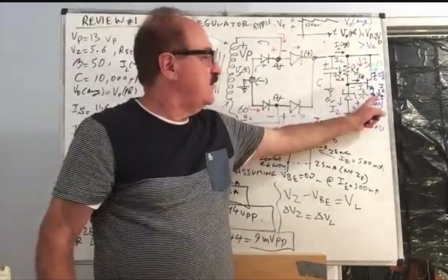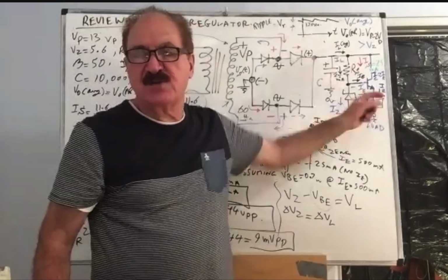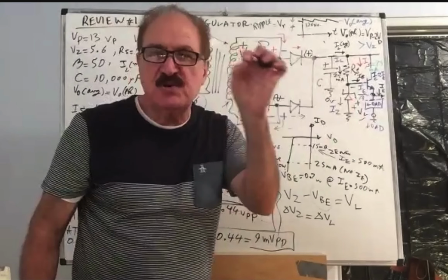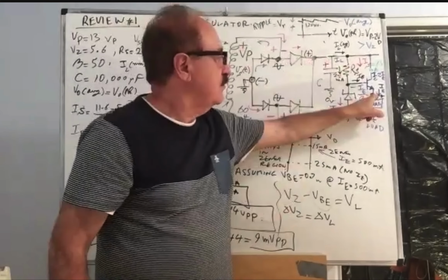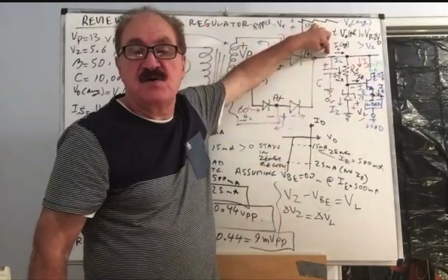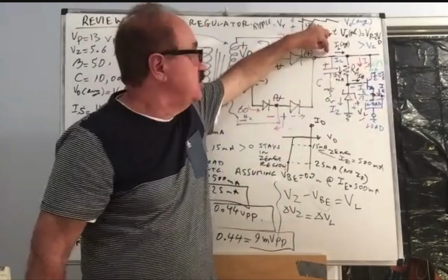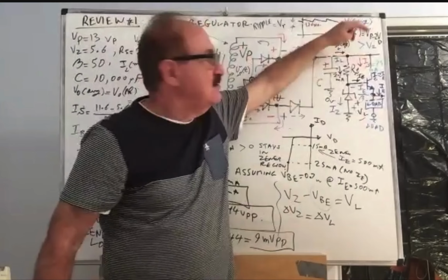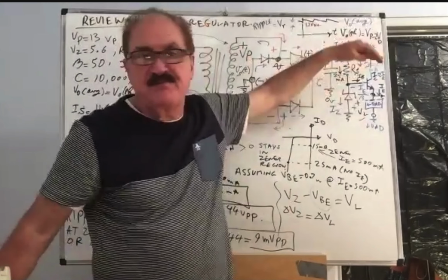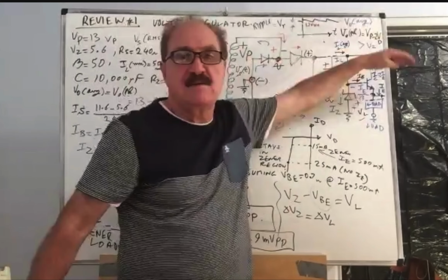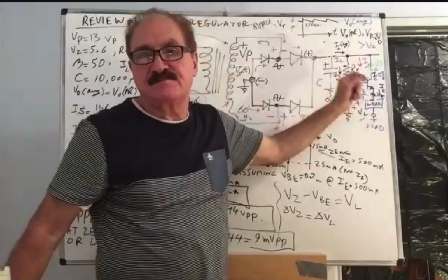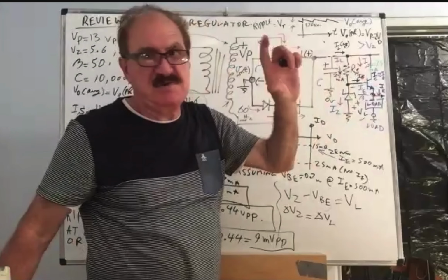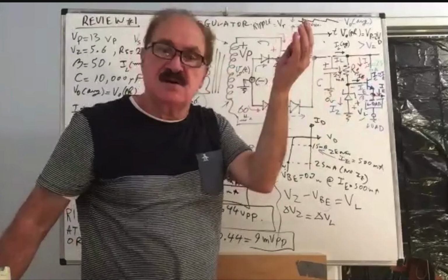Here we are getting a 4.9 volt regulated voltage with only 9 millivolt residue on it. It will not see the 440 millivolt residue, the main ripple at the collector, because the collector has no connection to the emitter. Collector can play, emitter can stay solid. VC will change, but VC change does not cause IC to change.